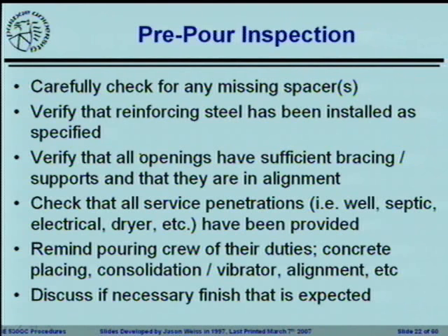Occasionally you'll see them, they accidentally get into the forms so they don't blow around on the construction site, but you want to make sure that everything is clear. Making sure that the reinforcing steel is installed as specified is really a crucial criteria because once it's cast, it's a major issue to go back in, take it out, and get it right.